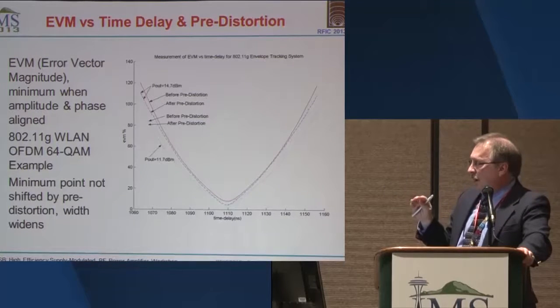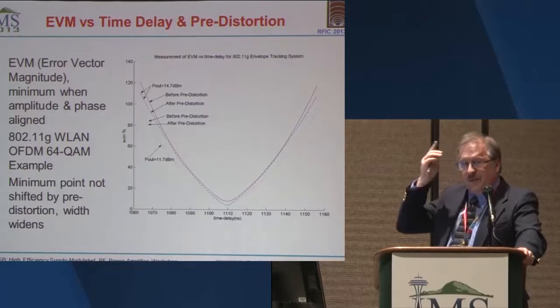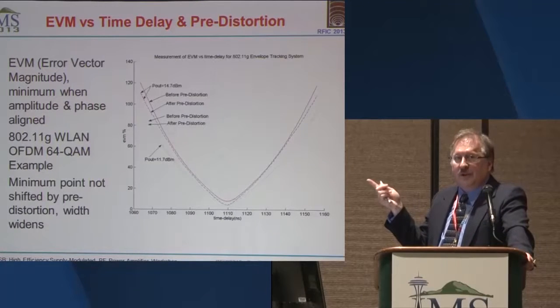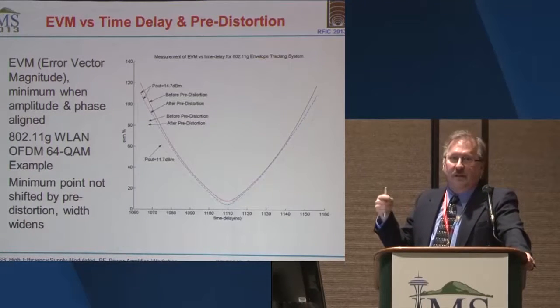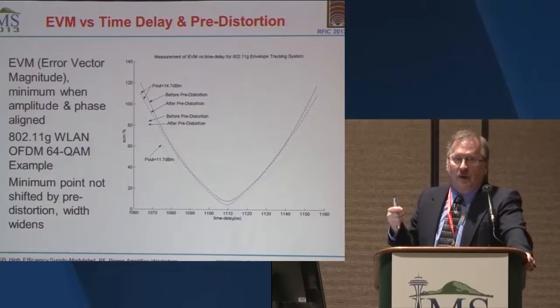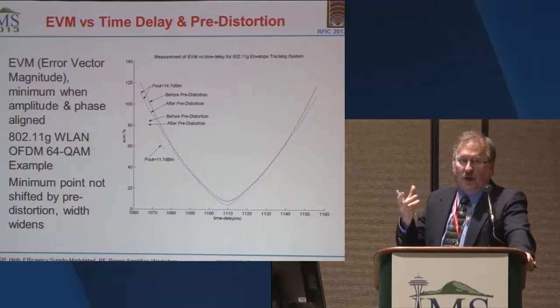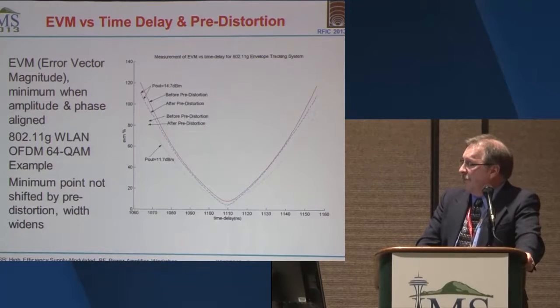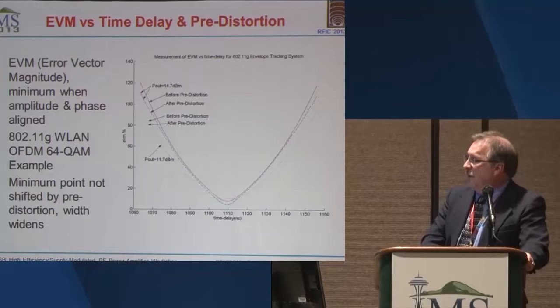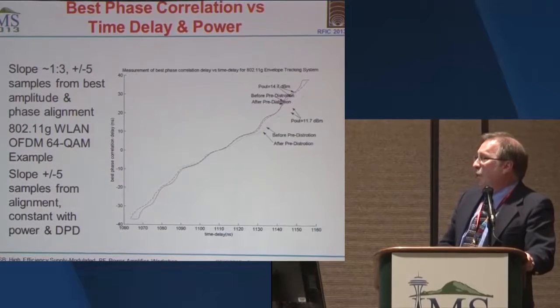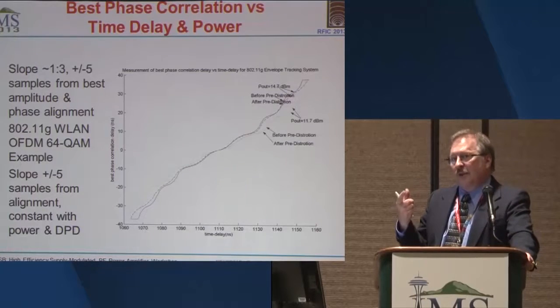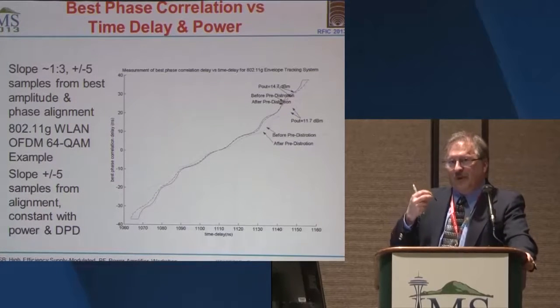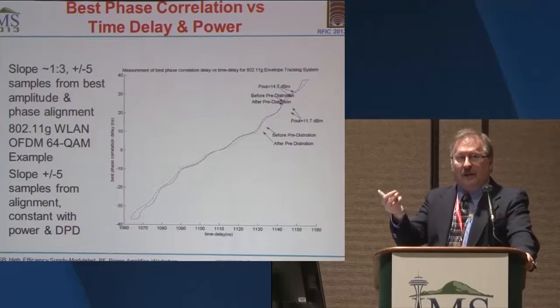And I think in many polar systems, this feature or this symptom of misalignment is actually used as a mechanism to do the time alignment because you don't have as much control on the amplitude of the RF signal. So this is a particular feature that's very, very helpful in confirming that you have found the optimal time alignment. And this leads to the observation that I made earlier: you can't just grab the number that it gives you, plug it in, and you're done.